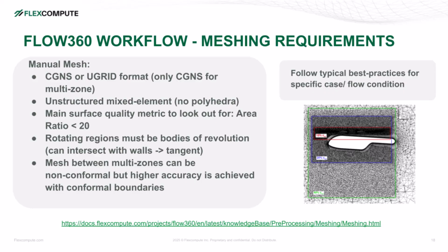If you are modeling rotating regions, they must be bodies of revolution. And mesh between multi-zones can be non-conformal, but conformal mesh results in improved accuracy.